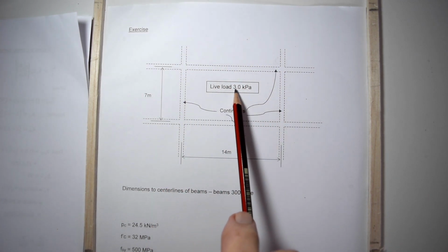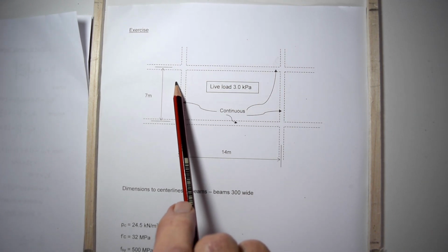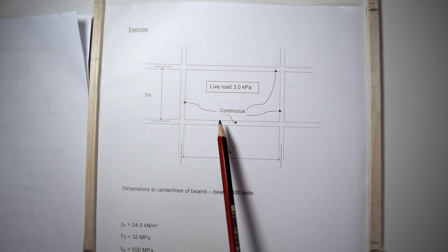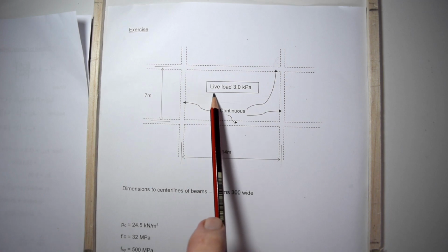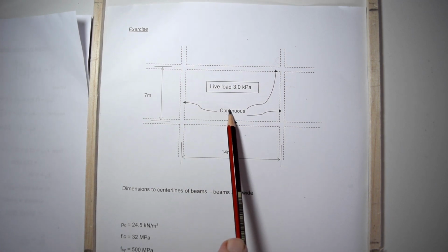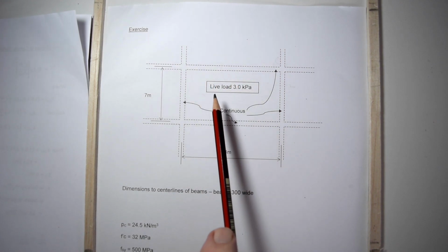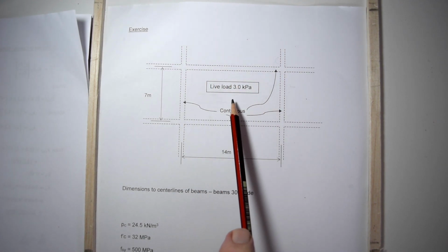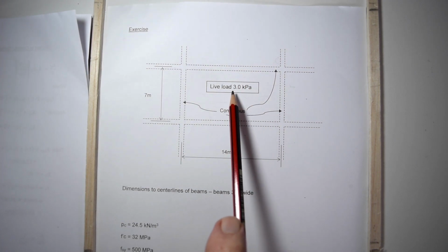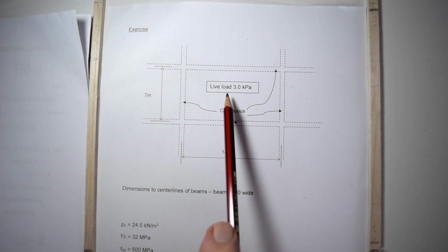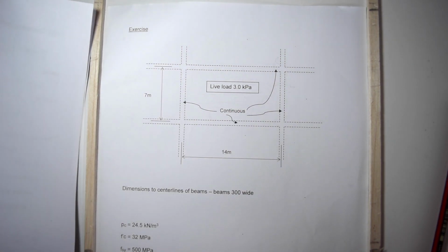So what we want to do is work out what the moments are on the slab, including the negative moments over the beams in both directions and the positive moments in the middle, because if you assume that this was elastic, which it is to a degree, it sags like this as it goes from beam to beam and sags between those two beams. So deflection, or the sagging amount, is quite an important criteria, but we will cover that today.